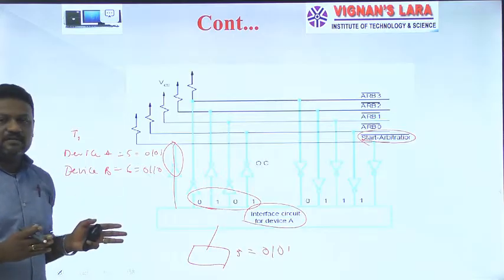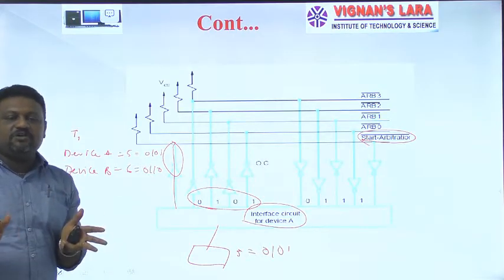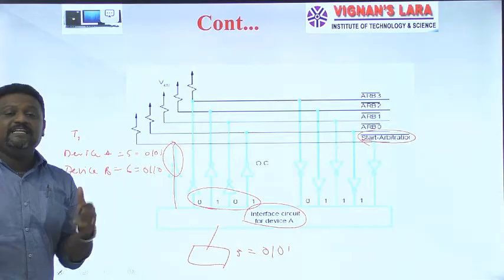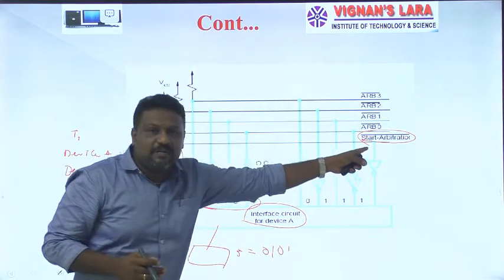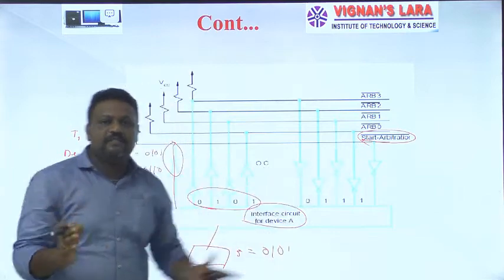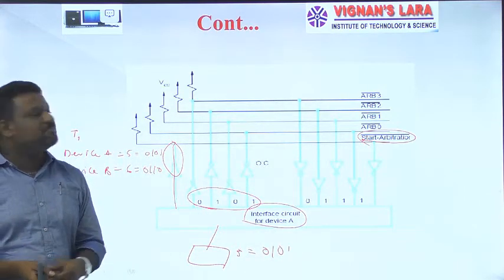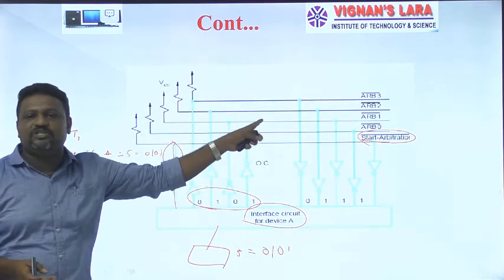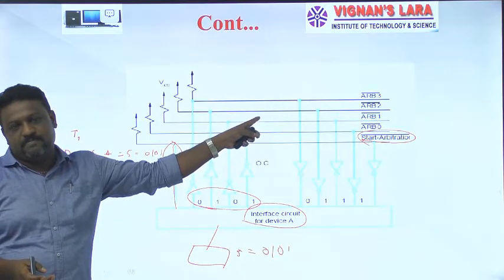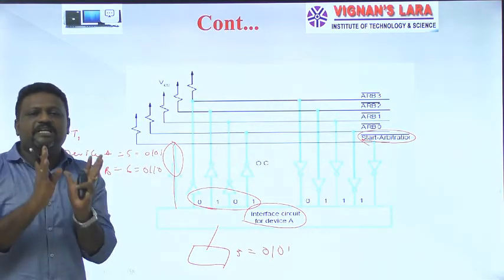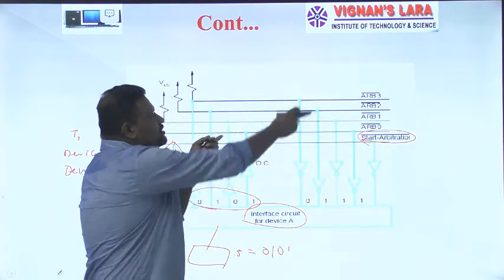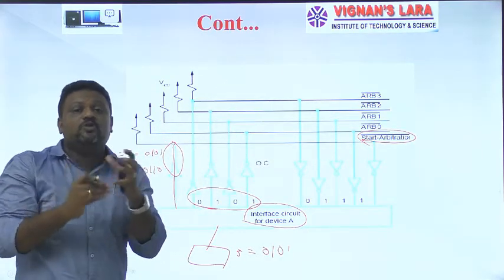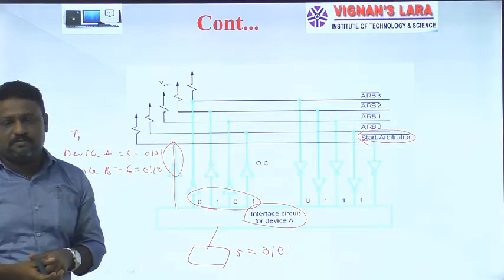So like this, whatever devices want a bus send their request signal. In that process, first they activate the start arbitration signal, followed by sending their identification numbers on these arbitration lines. Once that happens, the addresses placed over these arbitration lines are logically ordered.